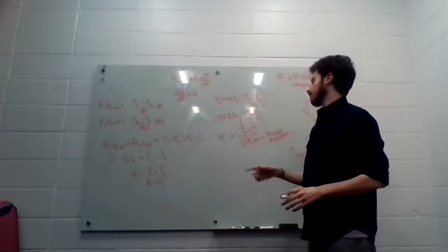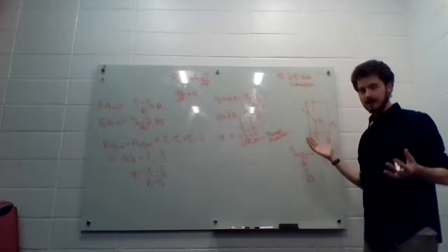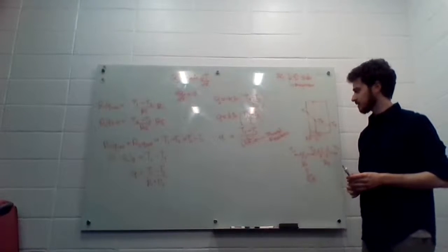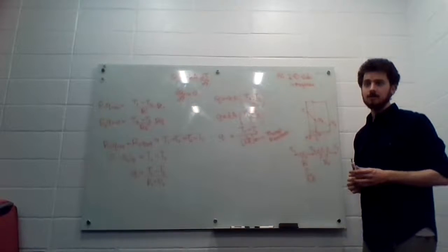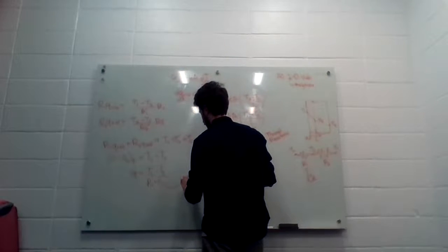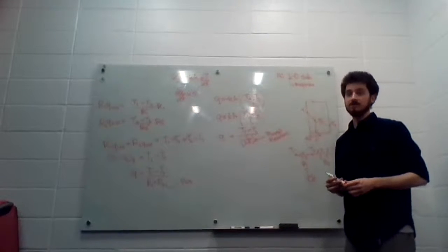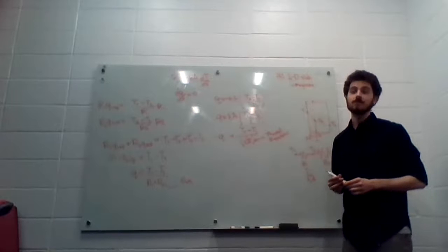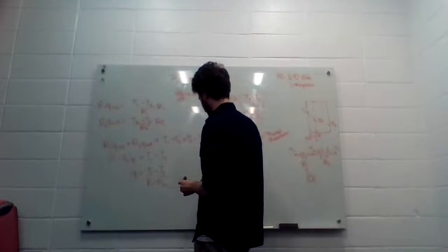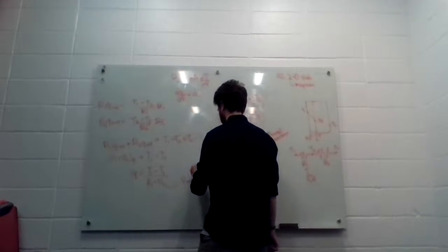So all we've done now is we've shown that this thermal circuit analogy, series circuit, series material, it applies, right? If you've got a bunch of different materials stacked up with different thermal resistances, you can just add those thermal resistances together and you'll end up with some equivalent. So for a building, you add up your gypsum and your plywood and whatever else, and you've got some R value for the wall, some big thermal resistance. This, by the way, thermal resistance is in units of Kelvin per watt.